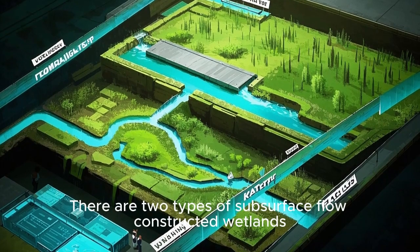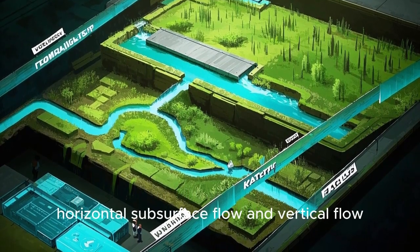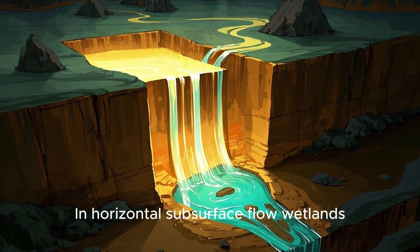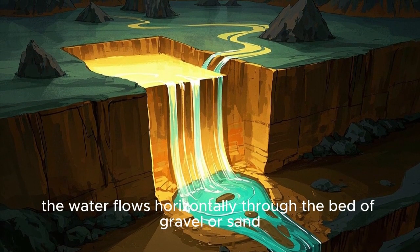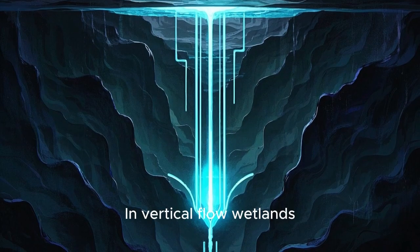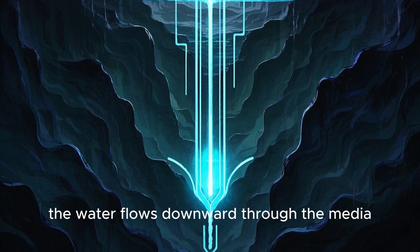There are two types of subsurface flow constructed wetlands: horizontal subsurface flow and vertical flow. In horizontal subsurface flow wetlands, the water flows horizontally through the bed of gravel or sand. In vertical flow wetlands, the water flows downward through the media.